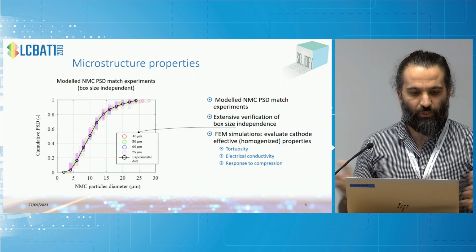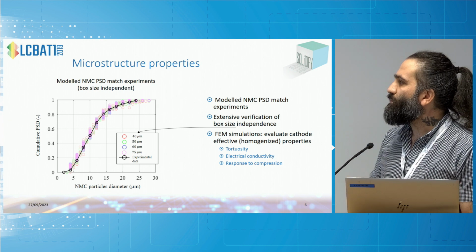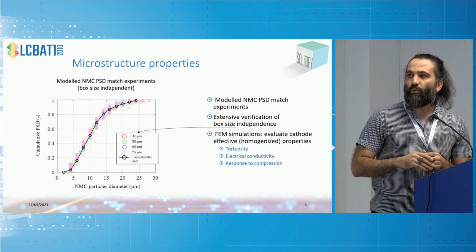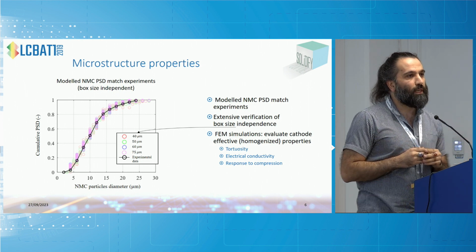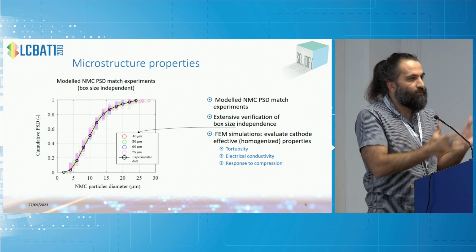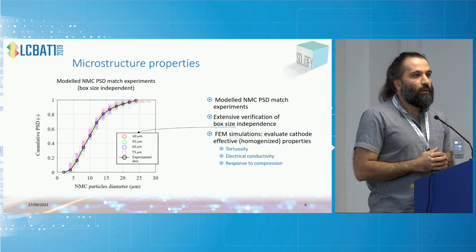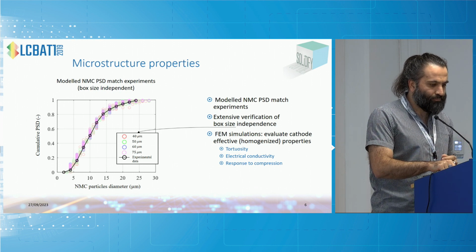the microstructure. The sort of validation that is quite feasible to do, for instance, is to juxtapose the particle size distribution that you can get from such a modeling with the particle size distribution of the active material, which can be provided by the material provider.